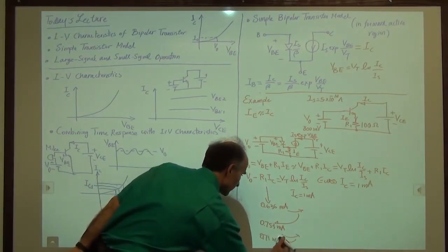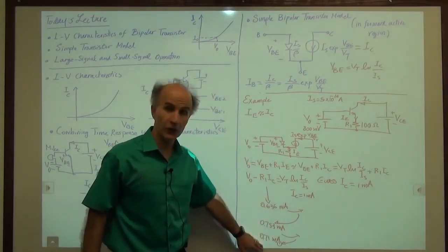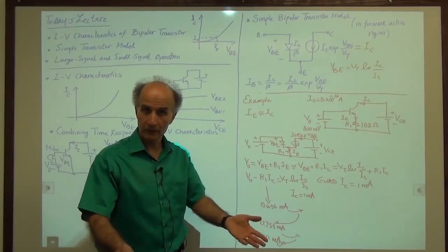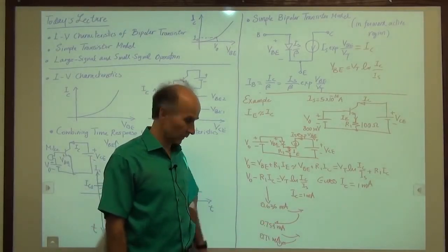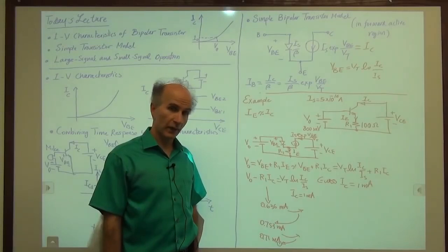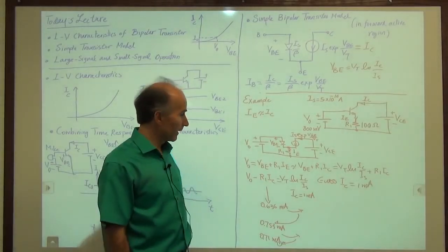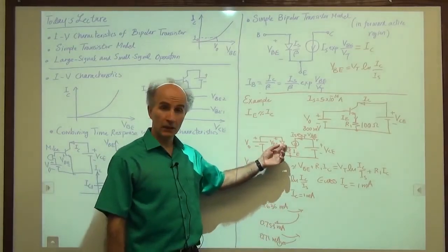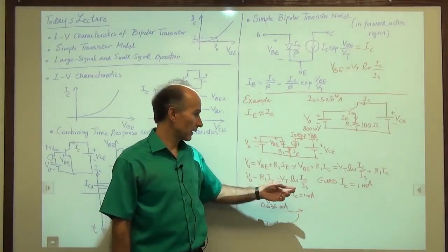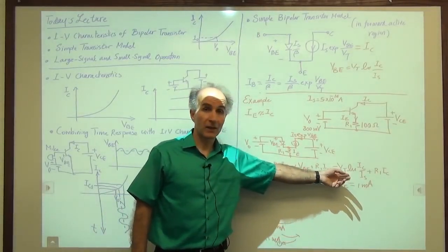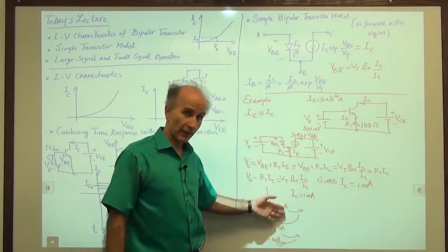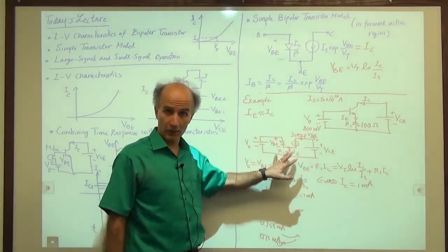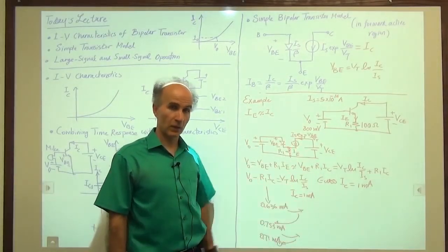So we see that we are gradually converging, right? The actual current is probably somewhere between these two, 0.73 milliamps or something in that range. Okay, so we can continue this, but that's the procedure that we use for iterations. So the purpose of this exercise was to show that because of the nonlinear function that we have here, and because we end up with an equation that does not have a closed form, we do have some mathematical labor. And you can imagine that once we have several bipolar transistors, the situation is more complex.